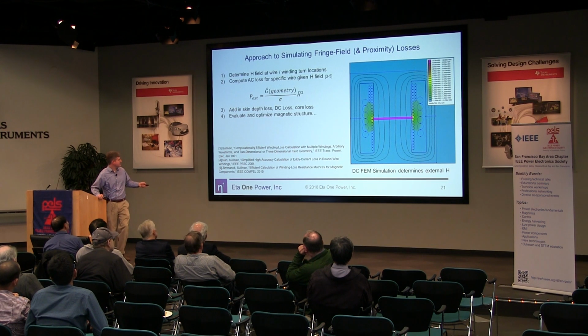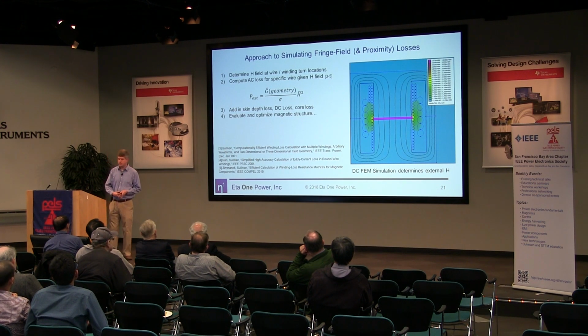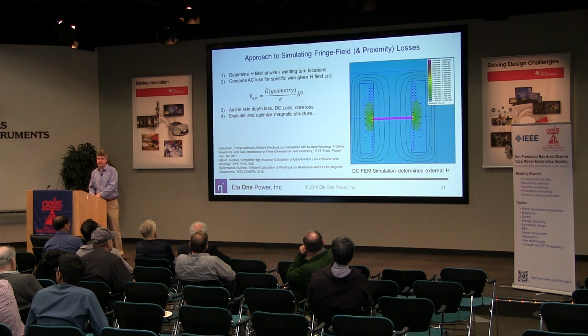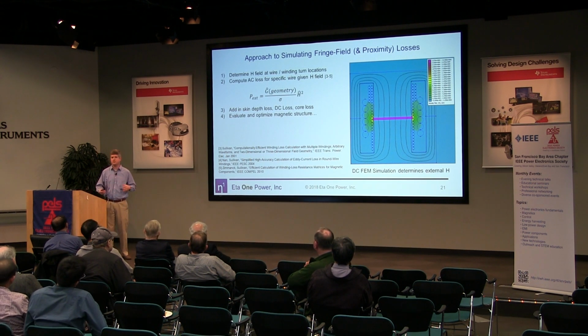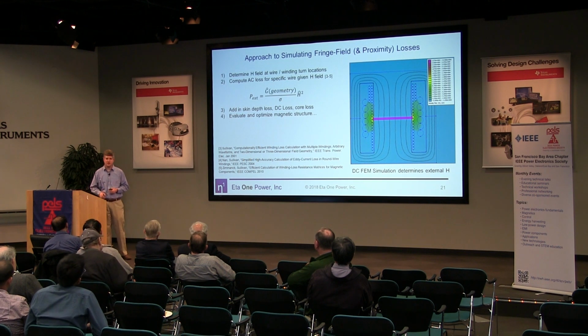And that's known as the square field derivative approach. There's a few references here talking about how that's done. So that can be done very quickly, and it's quite accurate. Sufficiently accurate, I mean, in terms of magnetics losses, plus or minus 20% is going to be as good as you're going to get, and as good as you're really going to need. But that gets you there.